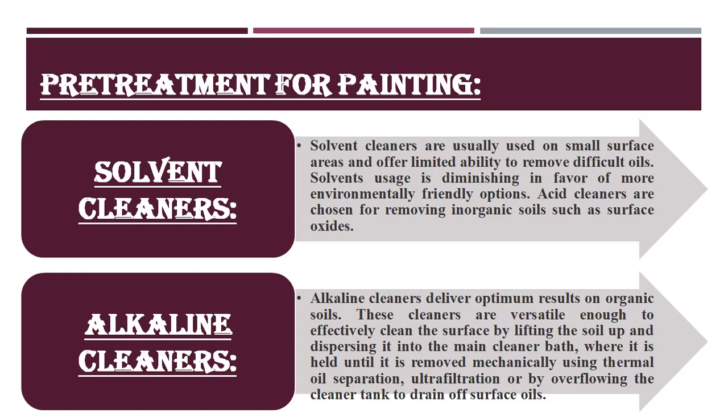These cleaners are versatile enough to effectively clean the surface by lifting the soil up and dispersing it into the main cleaner bath, where it is held until it is removed mechanically using thermal oil separation, ultrafiltration, or by overflowing the cleaner tank to drain off surface oils.